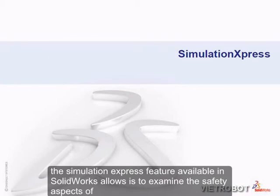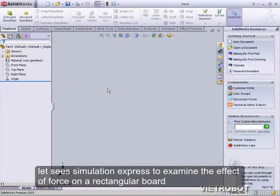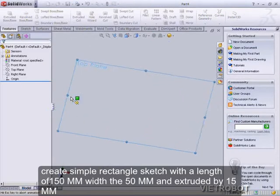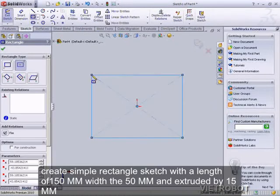The Simulation Express feature available in SOLIDWORKS allows us to examine the safety aspects of the product by applying forces or pressure to the specified areas. Let's use Simulation Express to examine the effect of force on a rectangular board. Create a simple rectangular sketch with a length of 150 mm, a width of 50 mm, and extrude it by 15 mm.